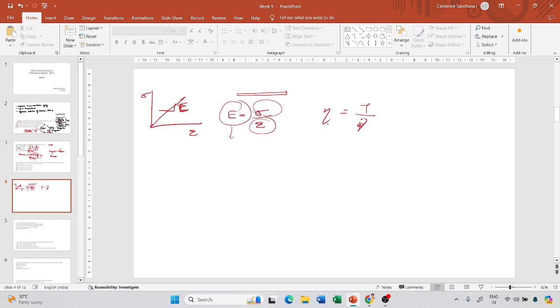Now if I keep changing this shear rate, and my viscosity does not vary, that is, I make a plot of shear stress versus shear rate, it is going to have the same behavior as that of a Young's modulus. That is, its slope is going to remain constant. So even if I keep increasing the shear rate, the slope is not going to vary, or the viscosity is not going to vary. This is called a Newtonian response.